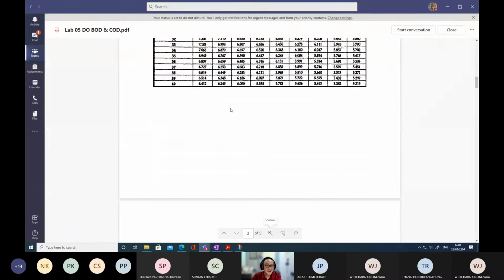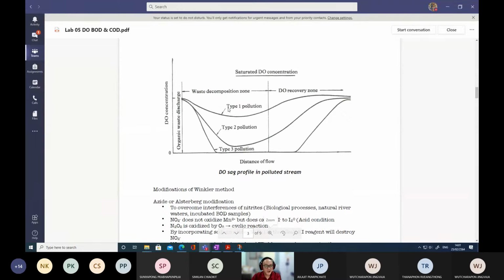That is also possible, but we only find that case when the surface water is contaminated or experiences algal bloom problems. An extra amount of algae grows in the ponds, and in the afternoon, like at 3 or 4 o'clock, the photosynthesis rate reaches the maximum. The end product of photosynthesis, we all know, is oxygen. So the oxygen concentration in the afternoon sometimes goes beyond 10 milligrams per liter. In that case we call it a supersaturated condition, not a saturated condition. It happens only when there is extra algae growth in that pond.